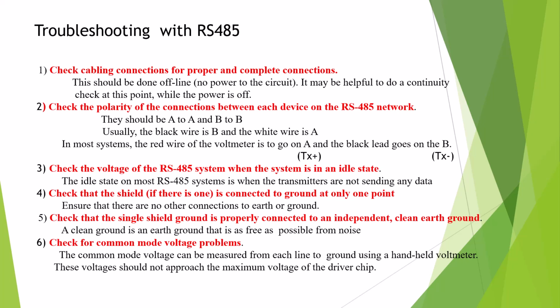Okay, so we check for common mode voltage problems. The common mode voltage can be measured from each line to ground using a handheld voltmeter. This voltage should not approach the maximum voltage of the driver chip.